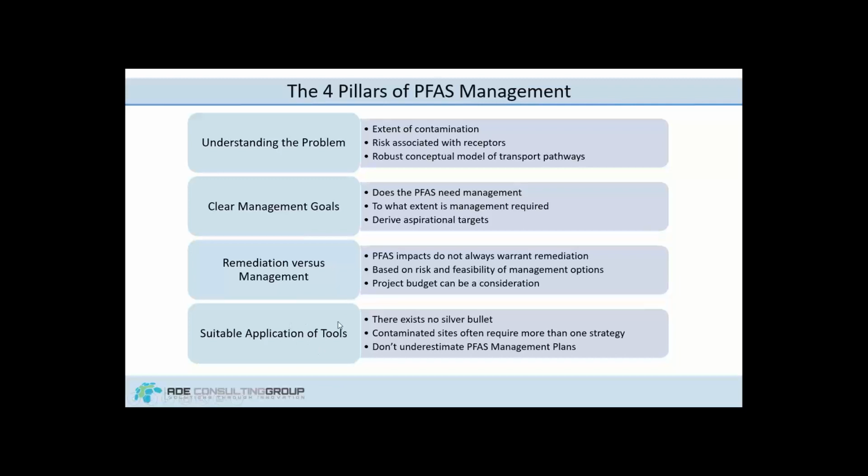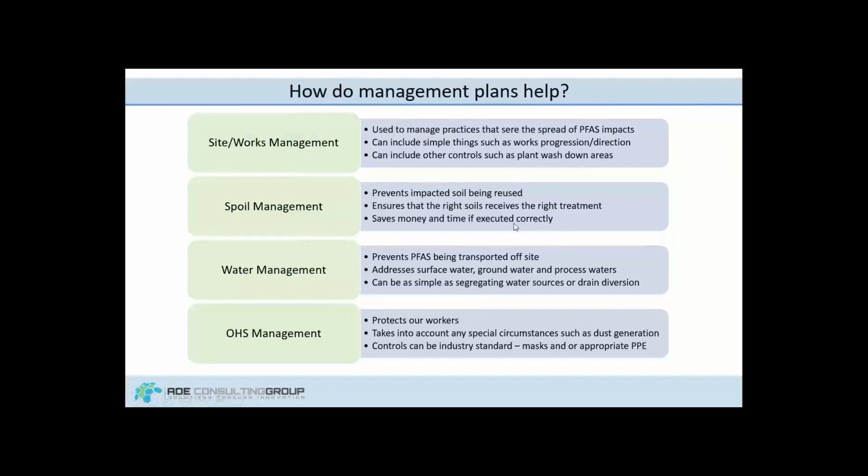And then lastly, suitable application of tools. There's no silver bullet. We do have to be careful of trying to use one approach or use a hammer for everything. Contaminated sites more often than not require more than one strategy, typically a source removal strategy paired with a management strategy for groundwater or waters. And then don't underestimate PFAS management plans. These small management plans can assist further with managing PFAS on site. So how do they help? Basically, we can change the way we work on site to reduce PFAS impacts and risk.